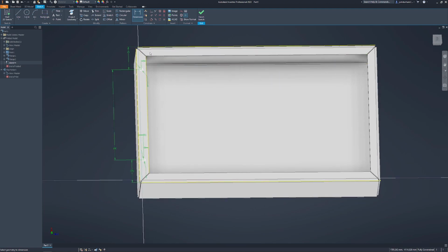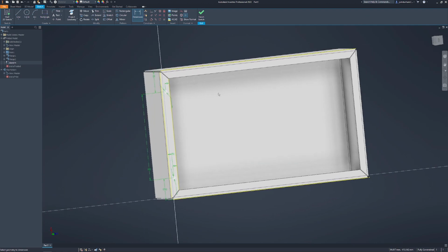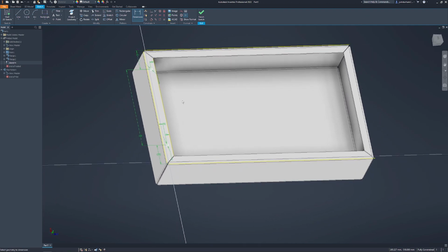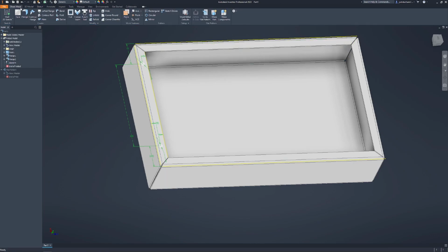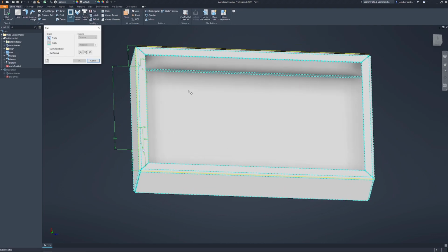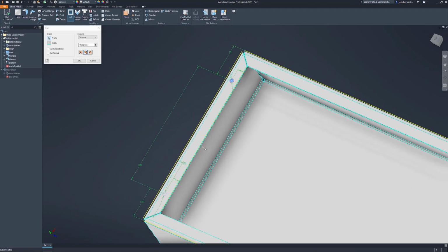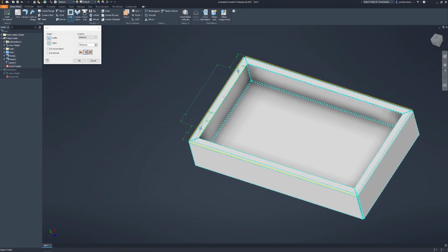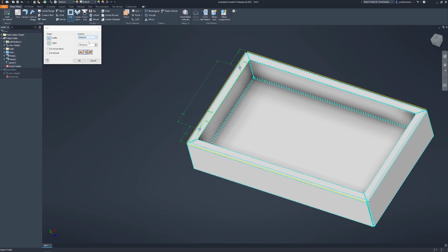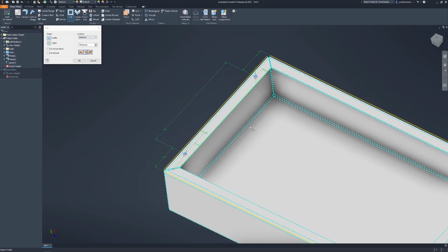Okay, so then what we'd go and do is create the sketches over there. In the same sketch, we can add in the circle there, circle there, circle, circle, circle. Or we can copy and mirror, but for now let's keep it simple and put in the circles there. So finish your sketch, sheet metal tools again, and we'll cut. So we want to select that, and if you'd added in your others, you'd select those as well at this point. So the extent of a cut is how far it's going to cut.